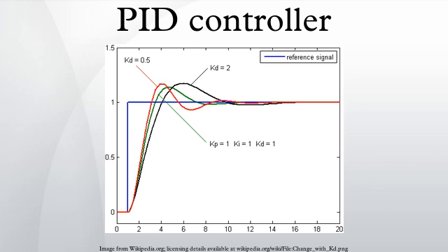Setpoint ramping. In this modification, the set point is gradually moved from its old value to a newly specified value using a linear or first-order differential ramp function. This avoids the discontinuity present in a simple step change. Derivative of the process variable. In this case, the PID controller measures the derivative of the measured process variable, rather than the derivative of the error. This quantity is always continuous. This modification is a simple case of setpoint weighting.